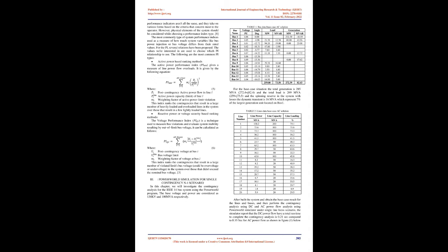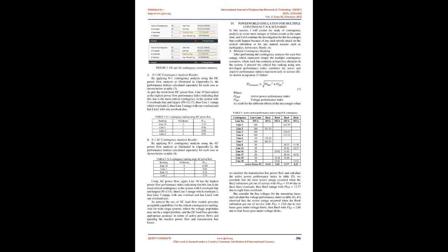ΔF_l = GSF_l,i × ΔP_i (1), where ΔF_l represents the change in power flow of line L when the generation at bus I goes out of service, and the new power flow on each line in the network can be estimated as follows: F_l = F_l^0 + ΔF_l (2). The outage flow F_l on each line can be compared to its limit, and those exceeding their limit are announced as violations. This would tell the operations personnel that the loss of the generator on bus I would result in an overload on line L11.